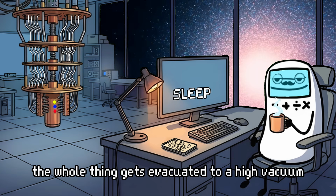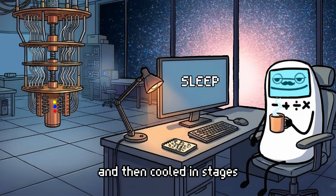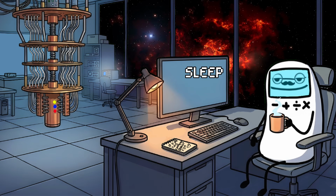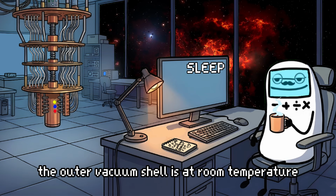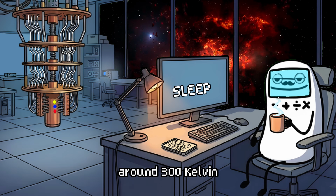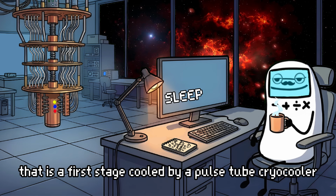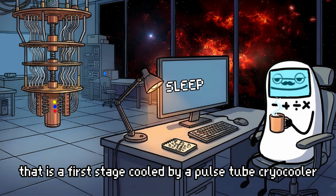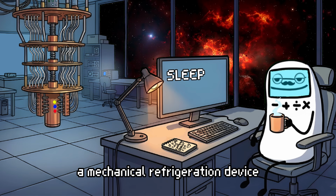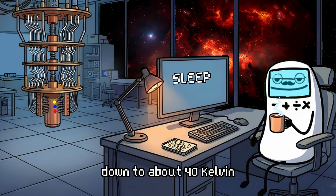The whole thing gets evacuated to a high vacuum and then cooled in stages. The outer vacuum shell is at room temperature, around 300 Kelvin. Inside that is a first stage cooled by a pulse tube cryocooler, a mechanical refrigeration device, down to about 40 Kelvin.